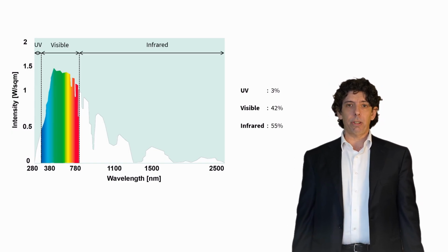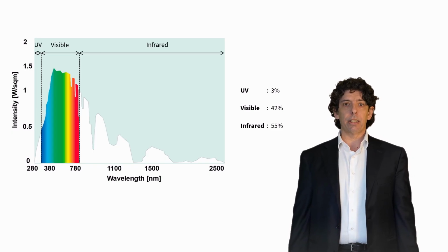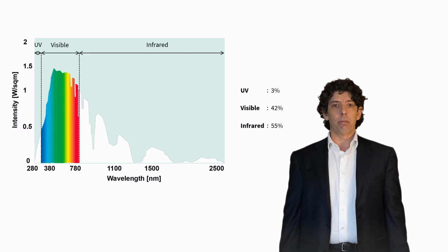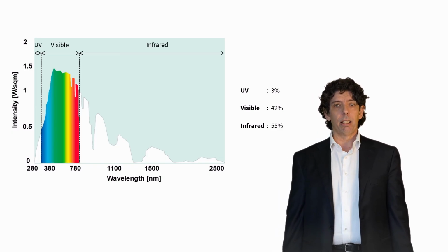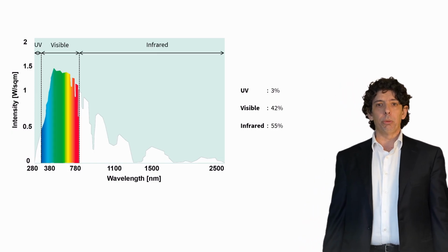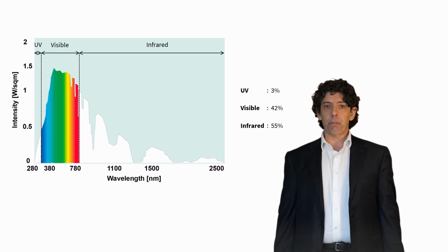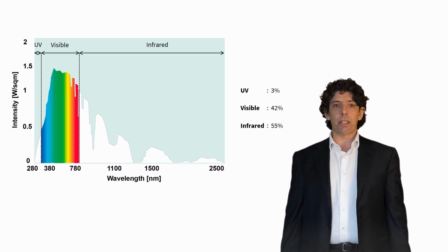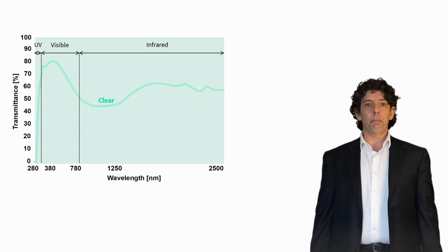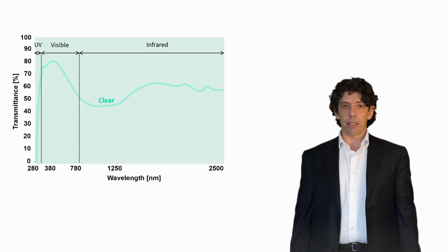The transmittance, reflectance, and absorptance factors of a glass are usually represented in a graph where the different ratios between incident and transmitted, reflected, and absorbed fluxes are reported for wavelengths comprised between 300 and 2500 nanometers. Starting from these premises, the behavior of a specific glass can be described through its whole spectrum or simplified by using its solar factor and visible light transmittance.